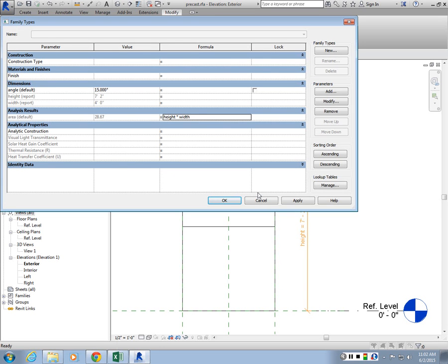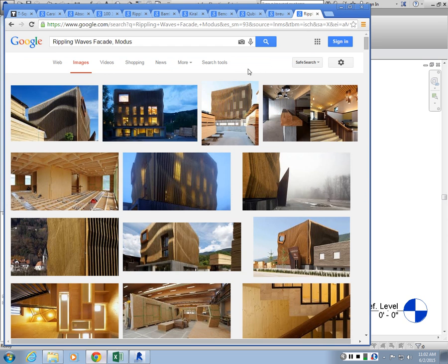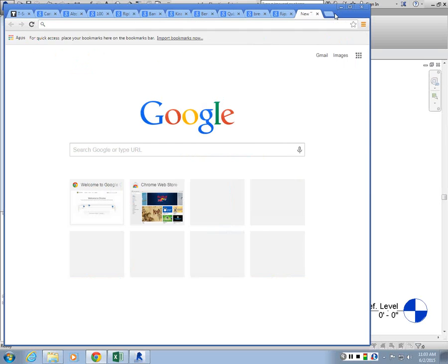Now the other thing I want to do is maybe use this area value to control the angle, right? And to do that, we can also create conditionals, like if statements. We can say if area is greater than this value, this threshold, use this angle, else use this angle. Absolutely. And there's a quick lookup for that.